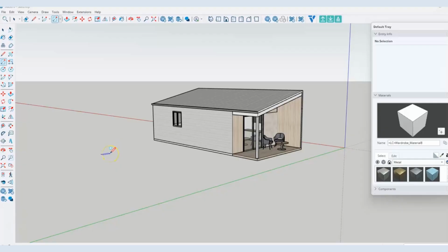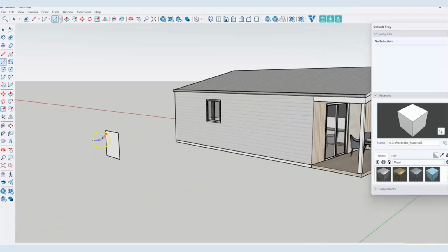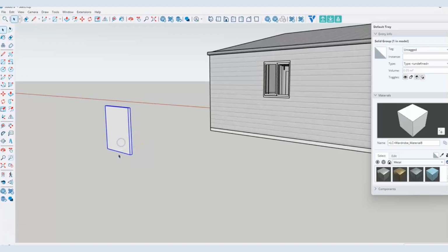So we're going to get textures from a variety of sources. To start with, I'm just going to create a rectangle with my cursor here, forcing it on a particular plane. I might just make it a certain size, 1000, 1000, and then I'll maybe give it a thickness of 50, and I might just group that. So I've just right clicked on it and grouped it. As you can see, it all lights up when I click it.